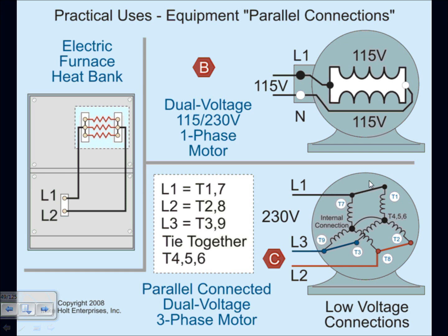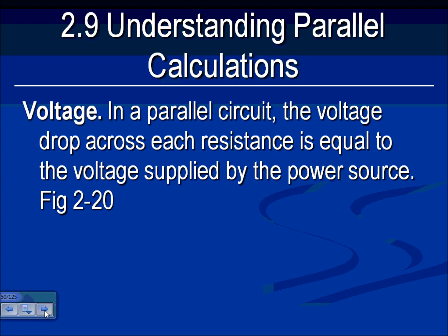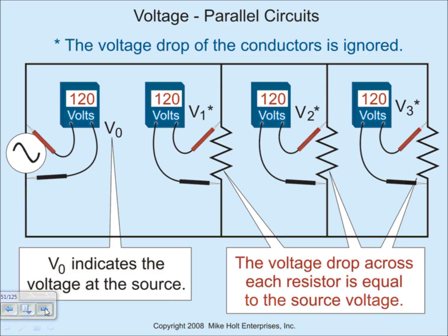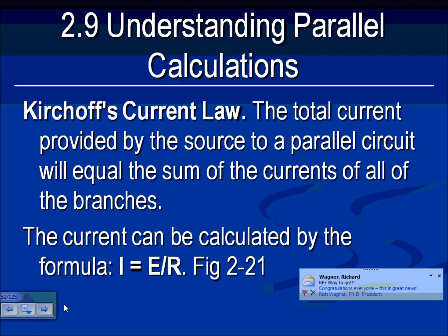Any question, guys, about paralleling the coils? As you can see, the coils right here are parallel. And this set of coils is parallel with the other set of coils. There's 2 stars in parallel to get you a lower voltage. So that's a major concept. Parallel circuit voltage. Voltage stays the same. This is why we choose it. Otherwise, good luck. The most important concept of it.